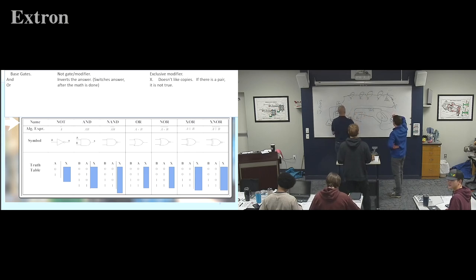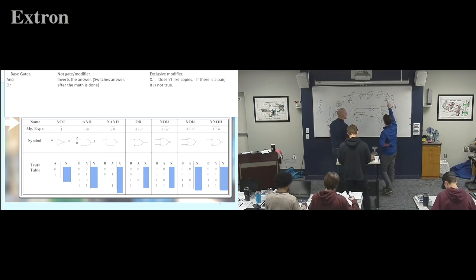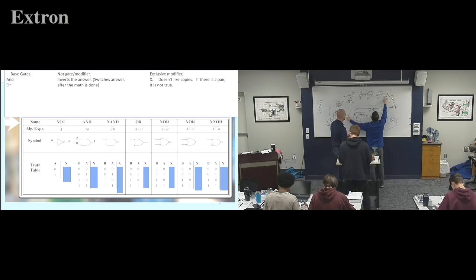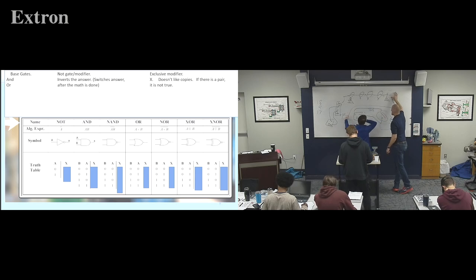Yep. Because if we put our little triangle under there, if my amperage is 0, I'm gonna have 0 up here. As soon as I change my amperage to, I don't remember what our amperage was, 3, now I will have some sort of voltage drop. You can figure that out. And this is all because using a voltmeter doesn't induce current flow. Correct. A voltmeter just tells you stuff. It doesn't change it. So once again, here to here, 0, there's nothing between. But here to here, with an open switch, would still be 0. Well, with an open switch, you got the 12.